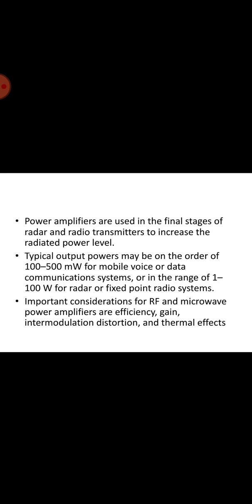So far we have considered only small signal amplifiers, where the input signal power is low and the transistor can be assumed to operate as a linear device. The scattering parameters of a linear device are well defined and they do not depend on the input power level or output load impedance, a fact that greatly simplifies the design of fixed gain and low noise amplifiers.